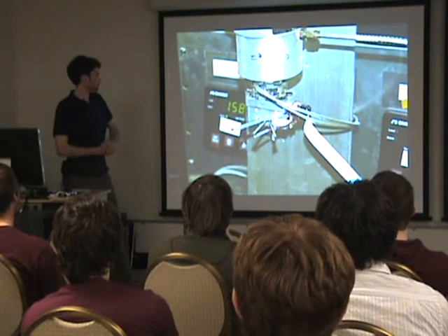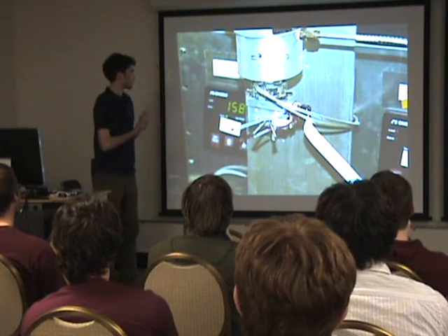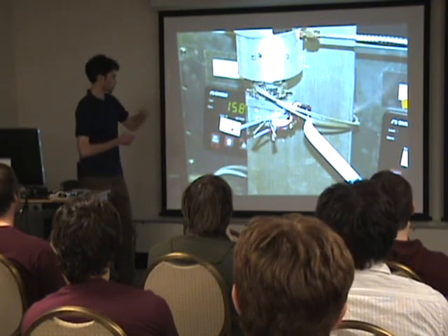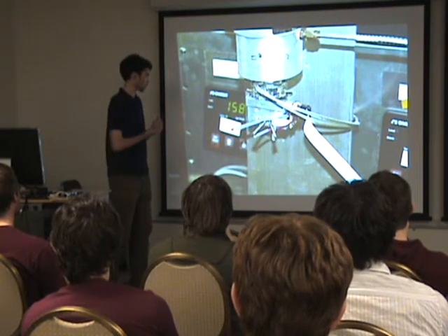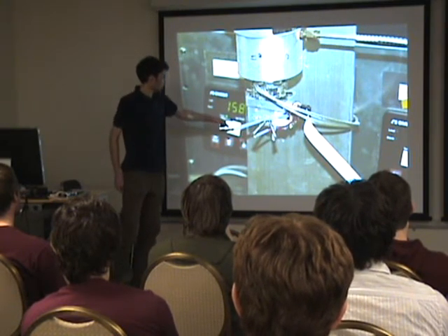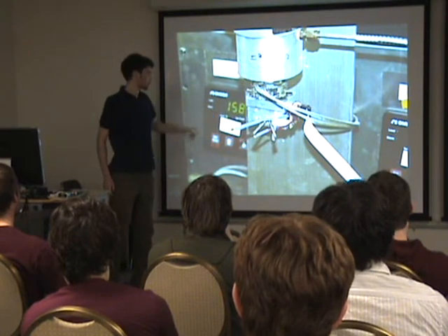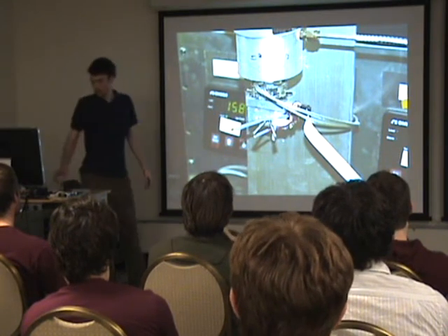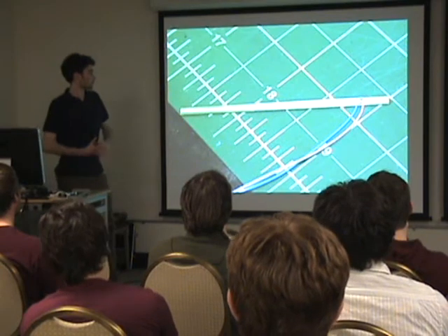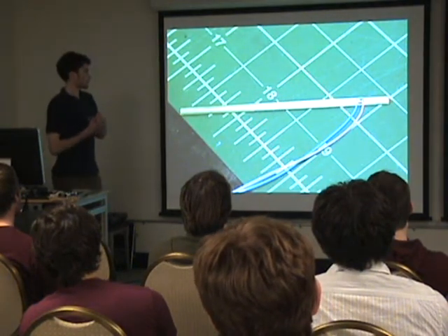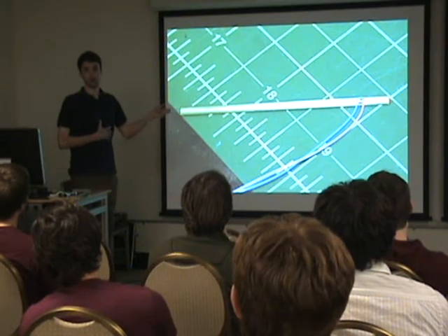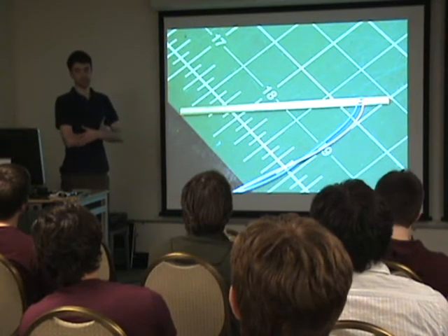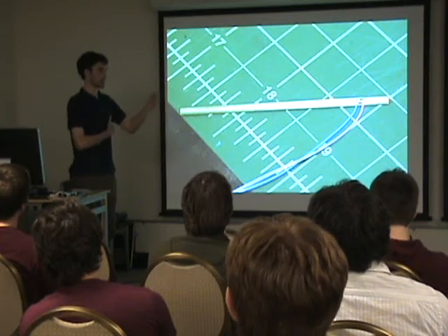And a final image here, we can see our heater pins and all the controls, well, the feedback part necessary to control our temperature. So we've got 30 gauge nichrome wire wrapped around our heater pins, and buried inside that head we have some really small temperature sensors. In this case, these are RTDs. I'm actually using LM35s, which are a temperature IC. So they're approximately the same scale.